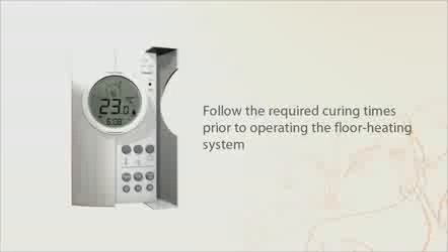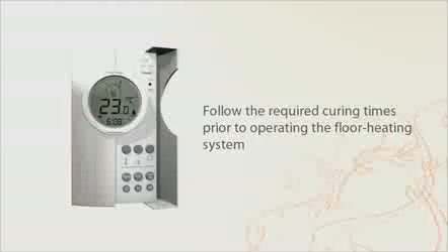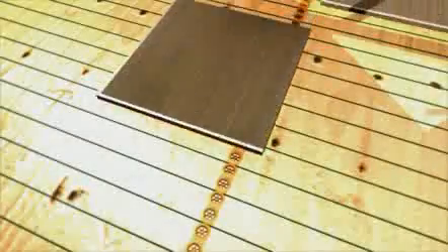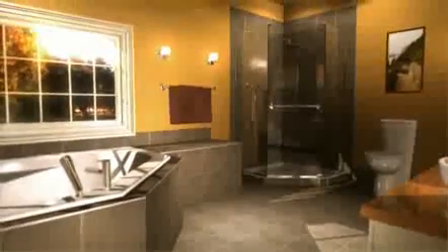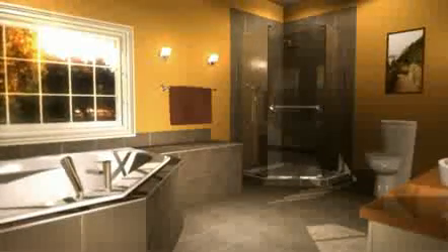To maintain manufacturer's warranties, follow the required curing times for the cement adhesive or self-leveling materials prior to operating the floor heating system. You are now ready to enjoy the soft and enveloping warmth of your Flextherm system.